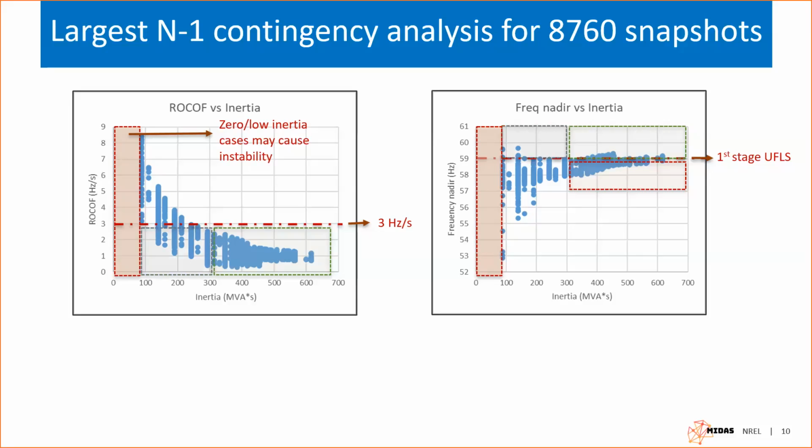Another observation here is the gray area. Those are cases with less inertia, but the system still can achieve a good record under the frequency nadir. So this study tells us we still need the inertia requirement in the scheduling stage, if we don't consider grid forming inverters. However, how to choose the proper inertia requirement will be sophisticated. We could propose some adaptive method, but before we go that far, another thing we would like to know is what's the cost to put an inertia requirement there and how much dynamic benefit it can achieve at the same time.